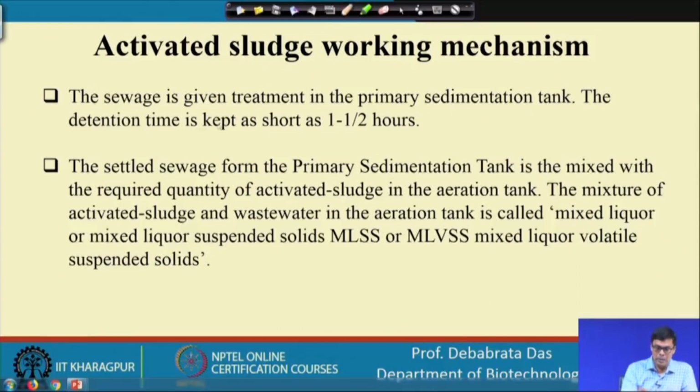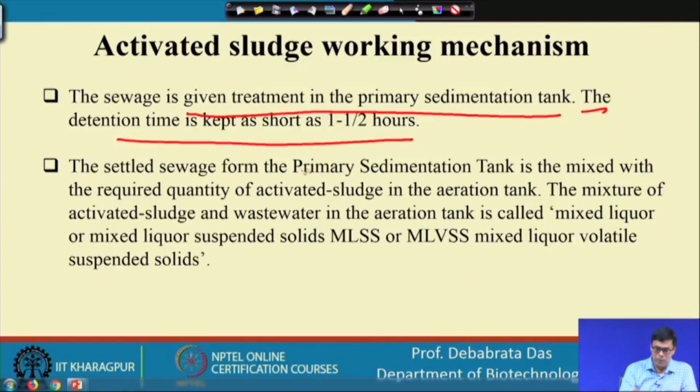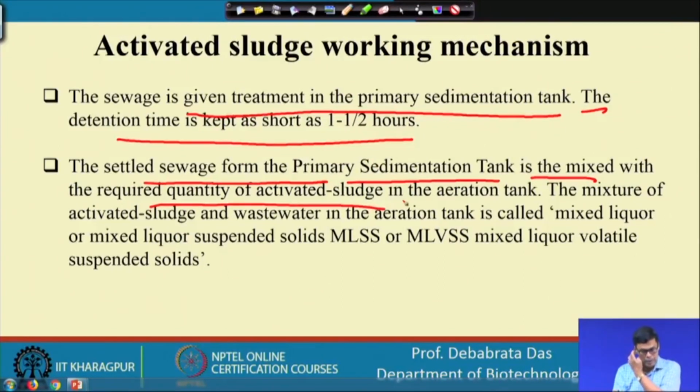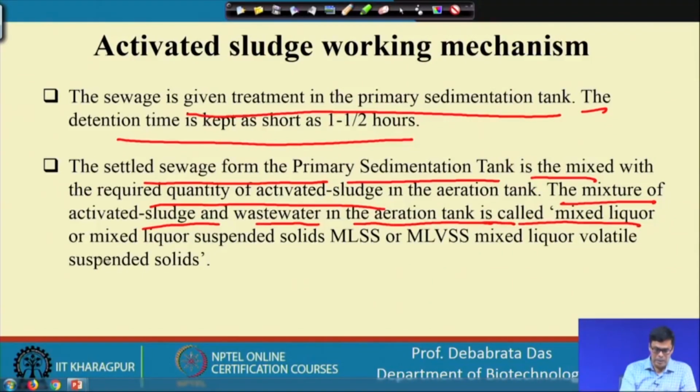The sewage is given treatment in the primary sedimentation tank, with a detention time of about 1 to 1.5 hours. The settled sewage from the primary sedimentation tank is mixed with the required quantity of activated sludge in the aeration tank. The mixture of the activated sludge and wastewater in the aerobic aeration tank is called the mixed liquor suspended solid, MLSS, or MLVSS, mixed liquor volatile suspended solid.